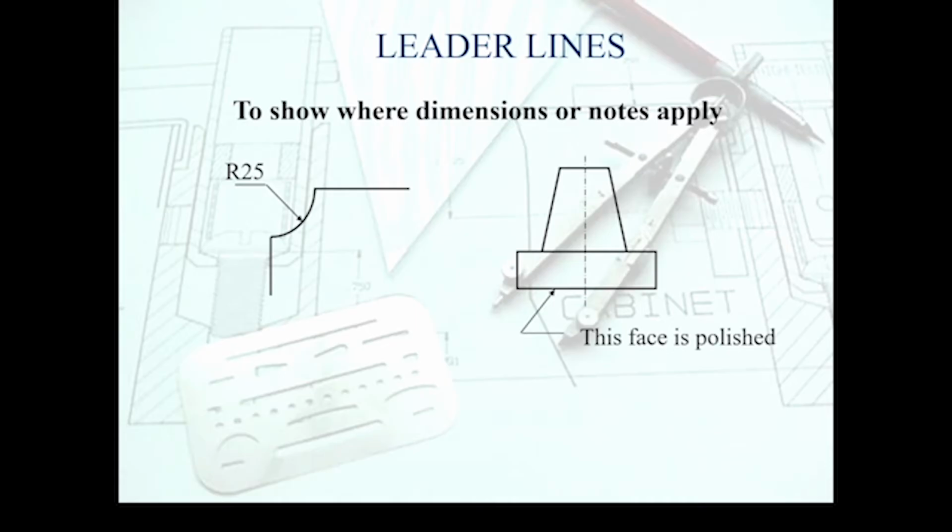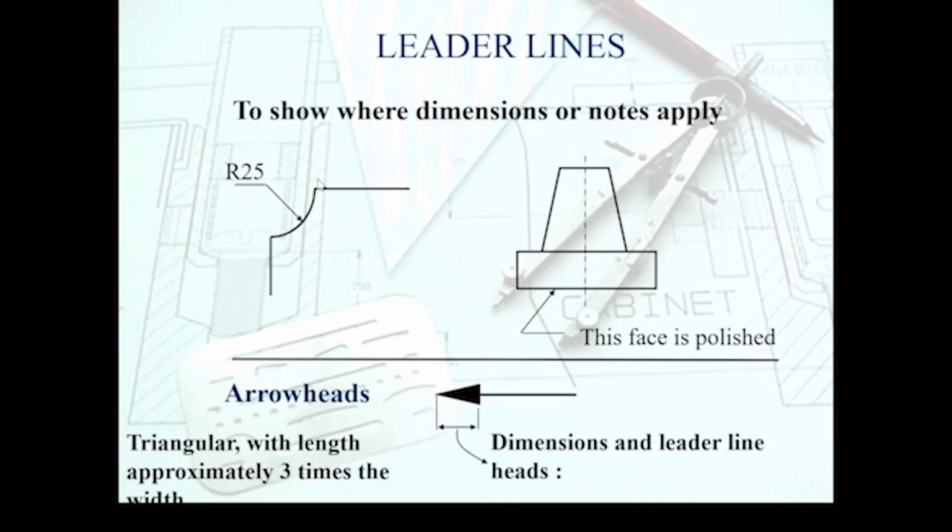A couple of other pieces of information you will probably have to use a call out option for in SolidWorks are called leader lines. This is where you can specify, literally click, drag, drop, and a text box pops up, and you can specify some details about that particular face, if you wanted it polished or painted, or like this, which we have seen previously.